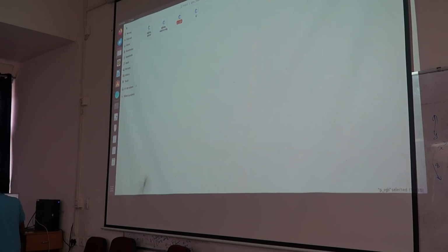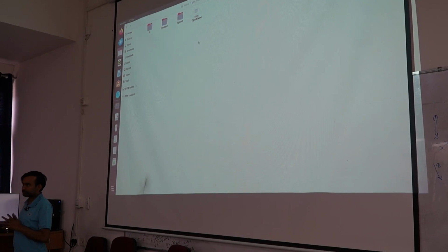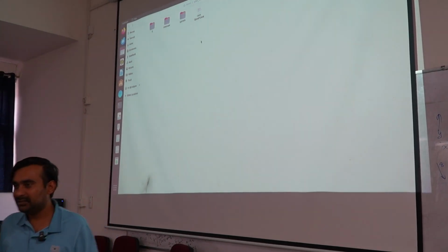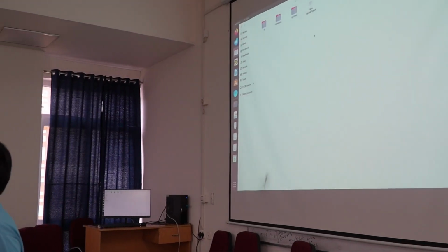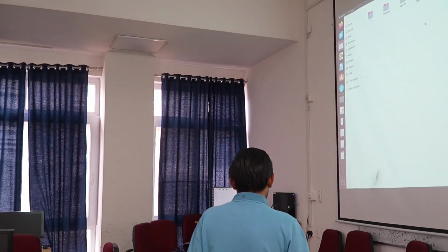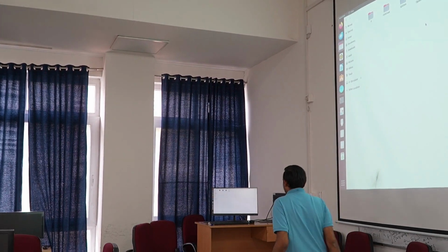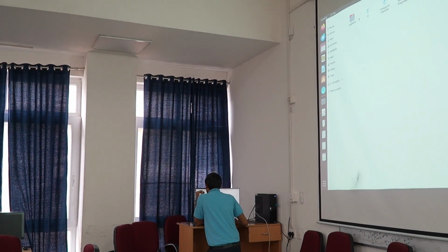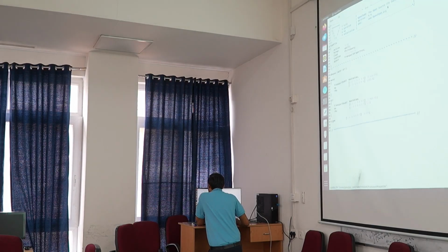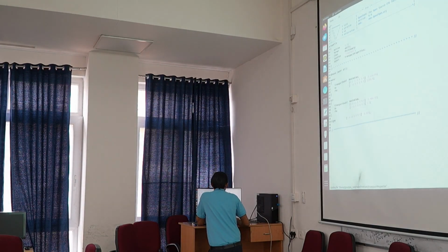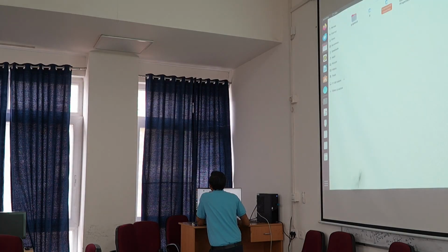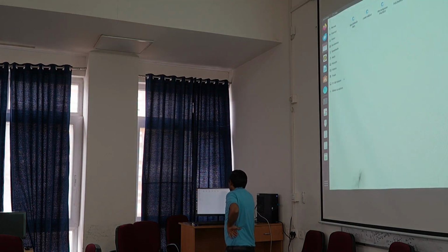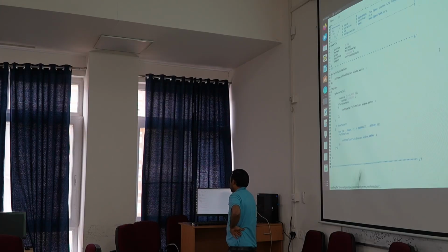After this, what do we need to do? After this, we need to tell our domain where our bubble is. To specify that, I will go to the system folder. In the system folder, please go to the setFields file.